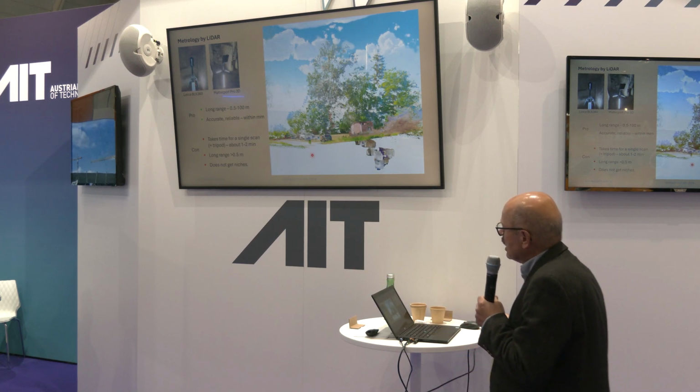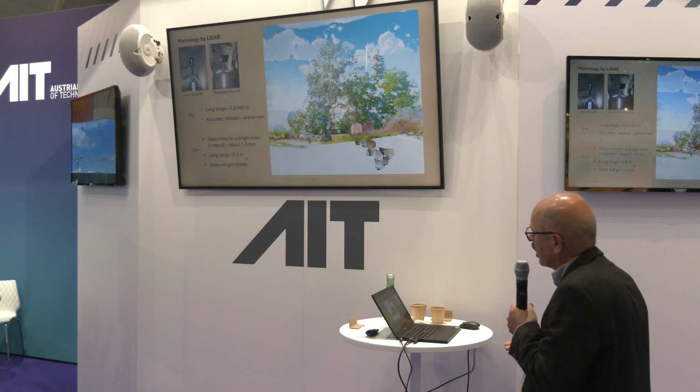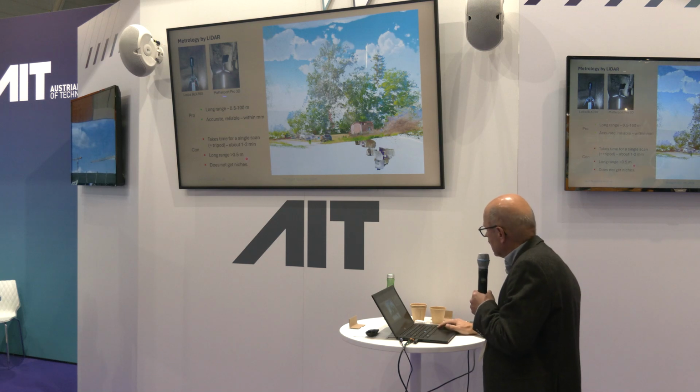It takes some time. You have to place the LiDAR sensor and move it to another place, because it takes 1 to 2 minutes for the sensor to capture all of the area. The disadvantage is also the long range, because in the cave you sometimes have places with very close distances, closer to 0.5 meters. And thirdly, it does not get into niches. So these are some disadvantages.